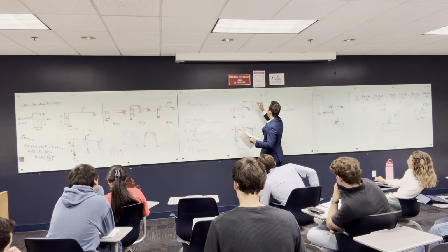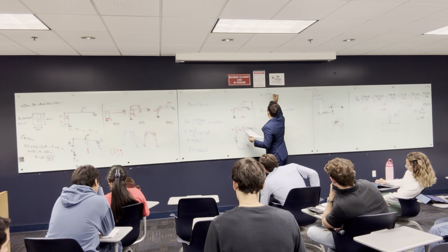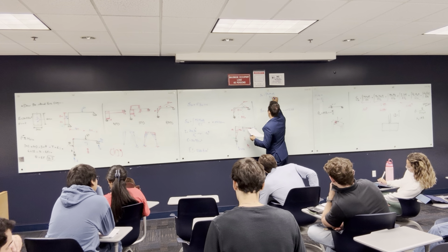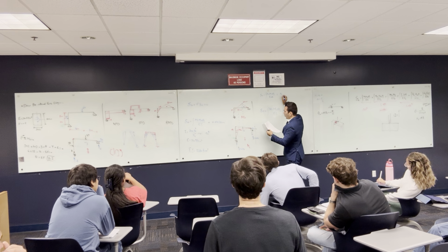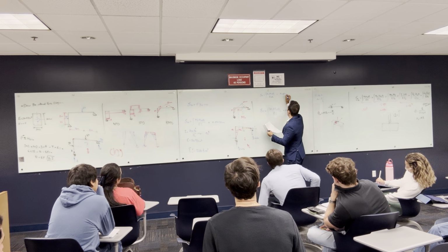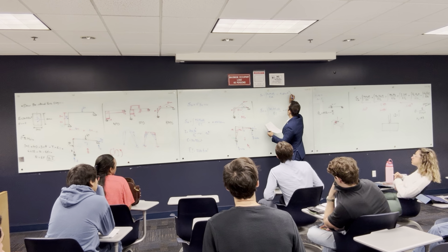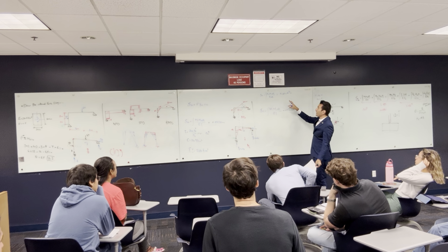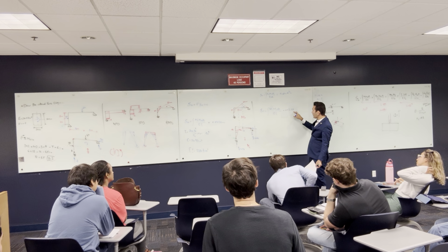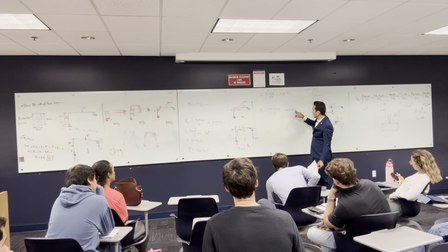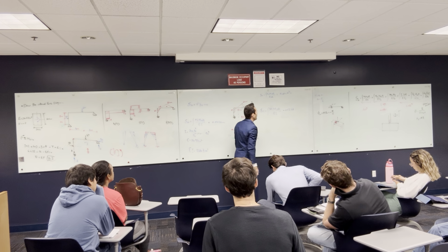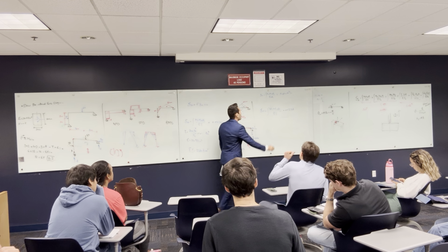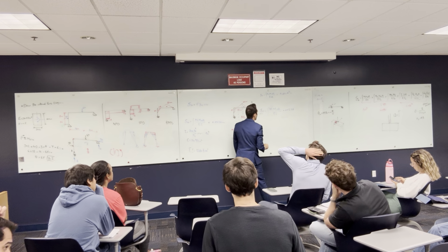By the way, that is the part that comes from bending. If you calculate the normal force term, N1 dl over EA, the one that I said I'm not going to do, the calculation here, look at it: 4.64 multiplied by 10 to the power negative 5 meter. Wow. So this force is not going to show up here until you come to a case like this one, so it's not that important. The most important one is the one that comes from the bending moment.